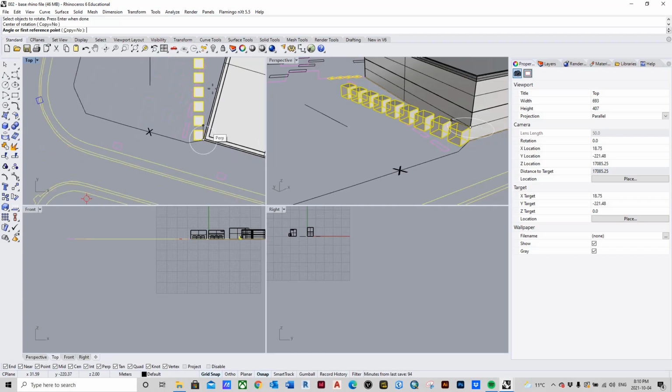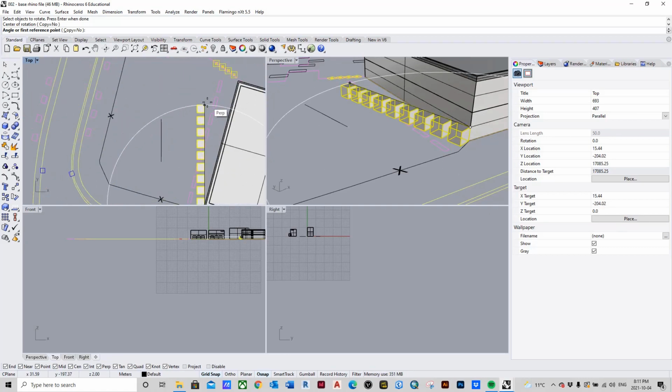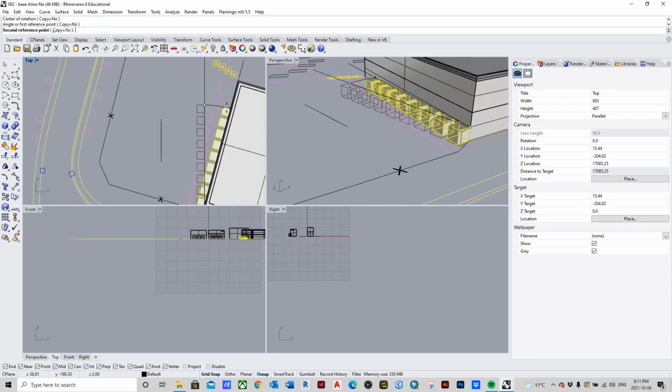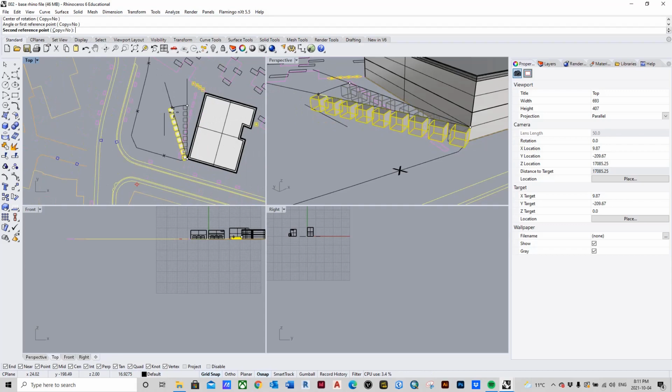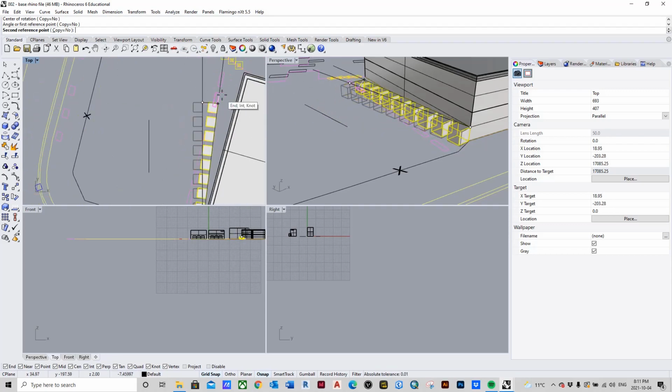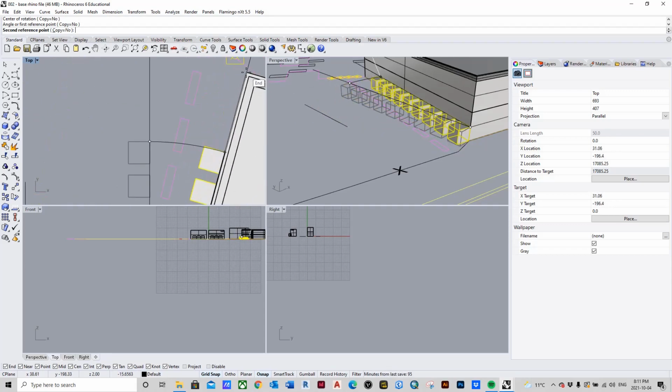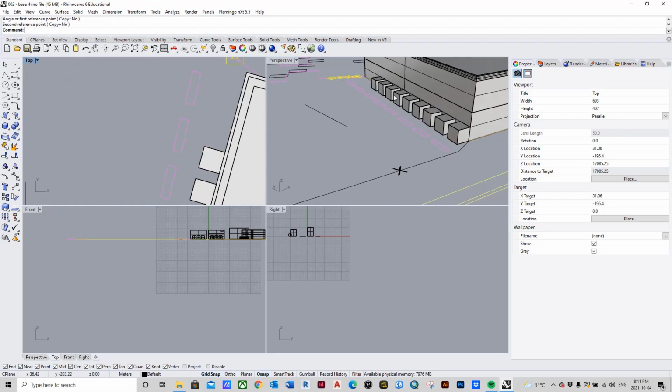and look, now it wants to turn everything we just selected somewhere around this radius. So we can really grab anywhere on here, but why don't we grab here? Right out to the very end of what we want to work with. And we'll hit select. And there you have it. Look at that. It automatically wants to rotate all of these together. We could just rotate one if we wanted to, but since we're going to be using these all for Booleans, we're going to take the whole bunch. So let's rotate. And look, now it meets the face of the wall just the way we need it to. We left click again, and now they're rotated.